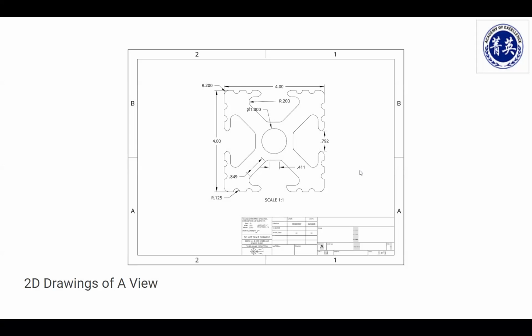This will be a 2D drawing of that same object of the single phase, right? See, with this drawing, you have all the details on how round the corner is, how long each of the legs are, all these little lightning cuts, what the radius of those are, and also specific dimensions of different angles, different lines, different holes. The hole in the center, for this instance, is 1 inch in diameter. And the gap difference here is 0.792. So they have very detailed information on a given subject.